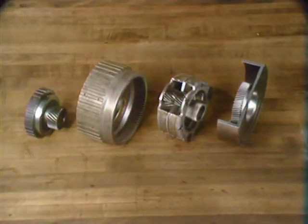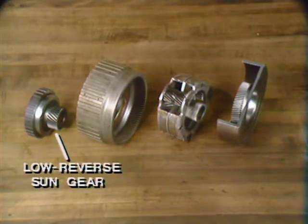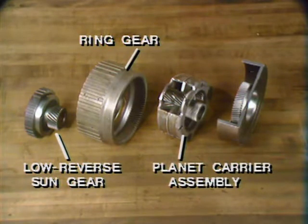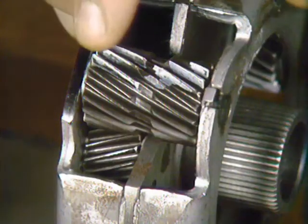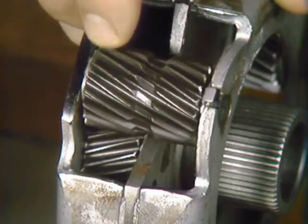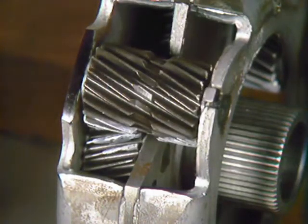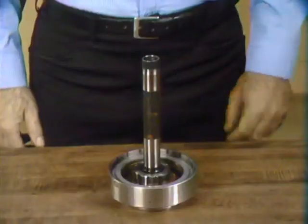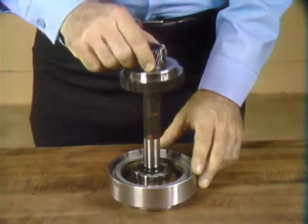Now we will look at the main planetary gear train parts, which are the low reverse sun gear, the ring gear, and the planet carrier assembly with two sets of pinions, 3 long pinions and 3 short pinions. Notice that each long pinion meshes with the short pinion and the forward sun gear. There are 2 ways to get power into this gear train.